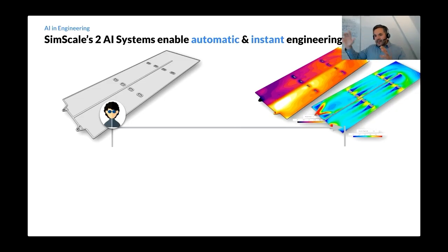We can see on the right, hopefully everybody has a sense now, you might not be in the design of cold plates, but in this case, we have a liquid, in this case water, coming through. And the engineering task here is, on the one side, we want to reduce pressure drop as much as possible to have the pump needed dimensioned as low as possible. But on the other side, we need to dissipate sufficient heat. It needs to be sufficiently conformal. You get the whole point. So it's an example design challenge.